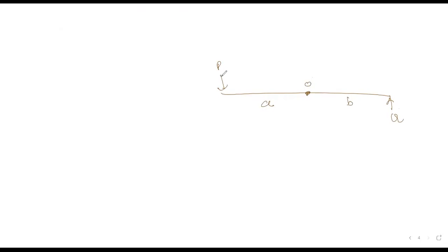Now, please tell me what is the direction of P force, upward or downward? Downward. Okay, in whatever direction your force is applied, extend an imaginary line in that direction, and rotate the arrow of the force about the point about which we are interested to take a moment. Now tell me what is the direction of your moment? Anti-clockwise. Negative, sir. Okay, fine. Negative. So this is, yes, negative.